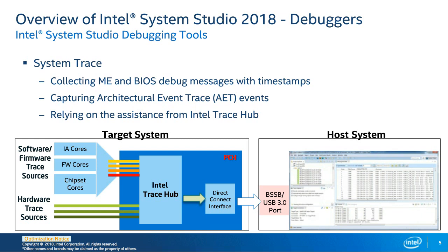Intel ME team, as the customers, always attach the ME trace logs when they report ME issues. But unlike BIOS logs, which can be output from the serial port, it requires Trace Hub's help to collect the ME logs. The Trace Hub here is a component in Intel PCH. It can collect debug messages from several sources and output the messages to Direct Connect interface.